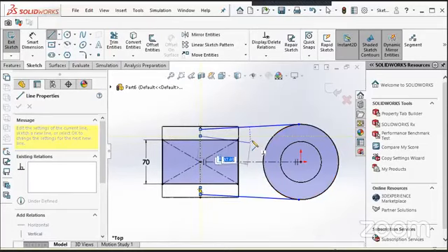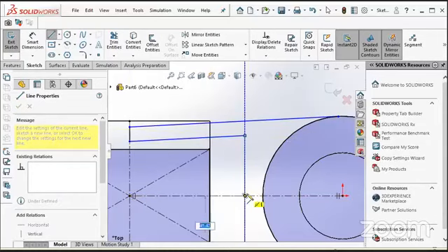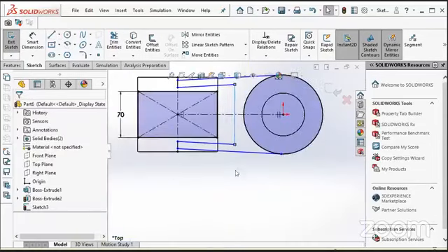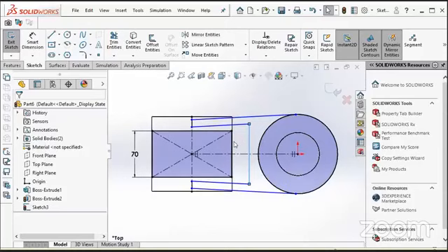I want to make both my lines parallel. So when I go to the nearest possible parallel, SolidWorks tells me that in this position, both lines are parallel. I'll click OK, and then done. Let me give the dimension to this one. But right now the protrusion I made is very small. So let me do it. I will click OK to my sketch.